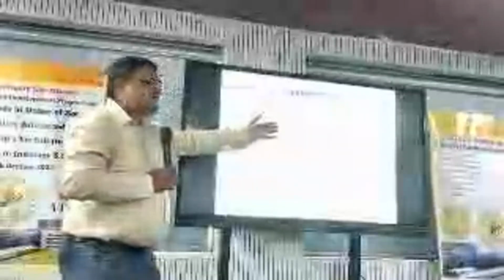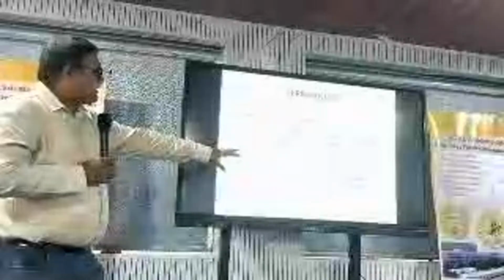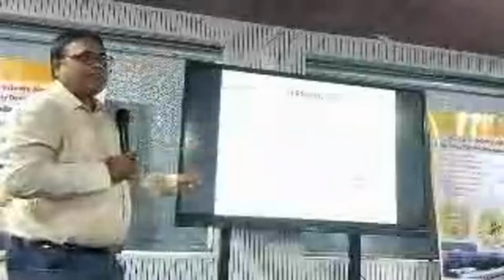So what is meant by resonance frequency? When the natural frequency and mode shapes as well as the forcing frequency, that is the driving frequency, both match, it will create resonance. So we should design the structures and equipment such that both frequencies do not match. And critical frequency is the frequency at which resonance occurs. Where the natural frequency and the driving frequency match, that is the resonant frequency. The corresponding speed is called the critical speed.